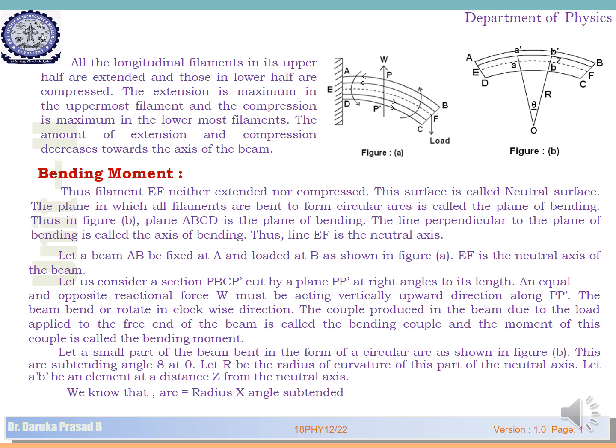This bending in the beam will not change the dimensions of the natural axis or neutral axis EF, whereas above this EF all the planes like AB, or any plane between E to A or F to B, are going to expand. Similarly, between E to D and F to C, they are going to contract. We will take one of the cases, that is only the expansion case.